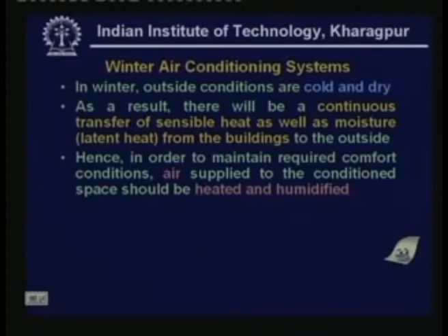In summer, outside conditions are hot and humid. So, what you have to do is supply air that is cold and dry. That means you have to generally supply cold and dehumidified air in a conventional system. Whereas in winter, it is exactly opposite. You have outside conditions which are cold and dry, so there will be heat losses from the building. To overcome the heat losses, you have to supply air which is hot and humid. That means basically you are looking for a heating and humidification process.